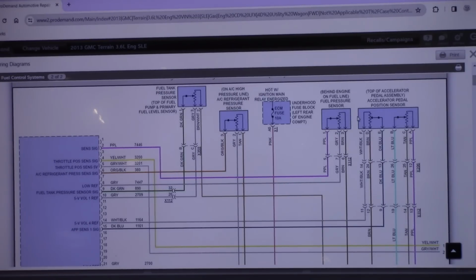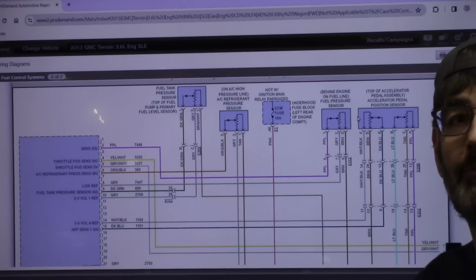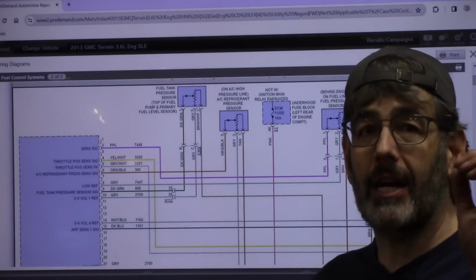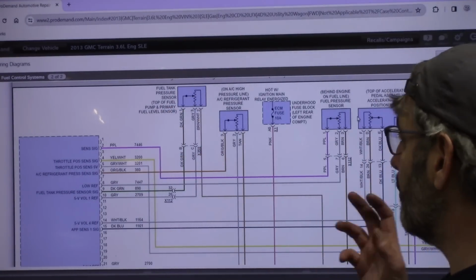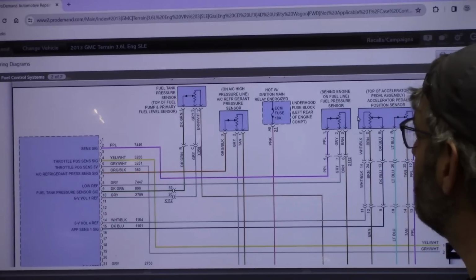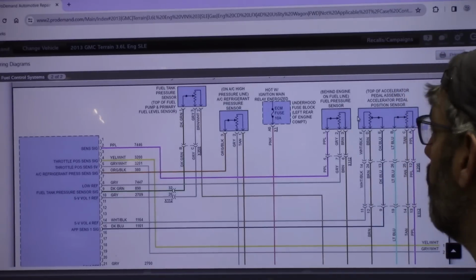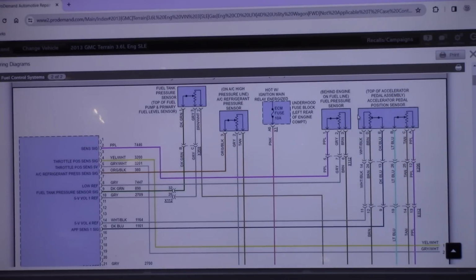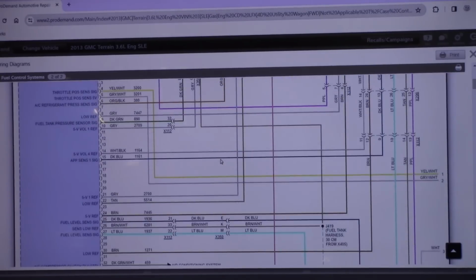How are we going to know, first of all, if we find something even that is power side switched? Well, one of the things is that it's going to have most likely a constant ground, and it's going to be some kind of device that's going to be powered through the computer if it's always grounded. So I'm kind of more looking on the name of the device because I just happen to know which ones are more likely to be.